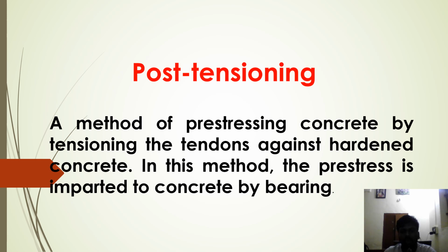Post-tensioning is a method of pre-stressing concrete by tensioning the tendons against hardened concrete. In this method, the pre-stress is imparted to concrete by bearing.